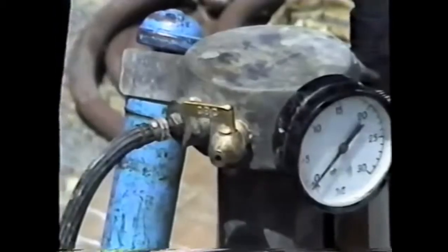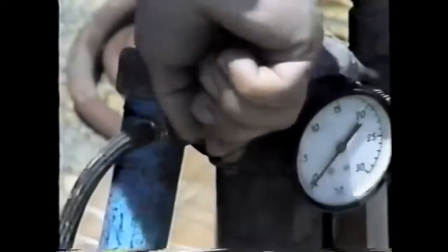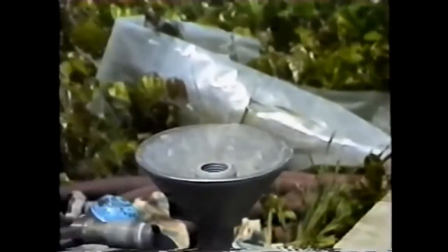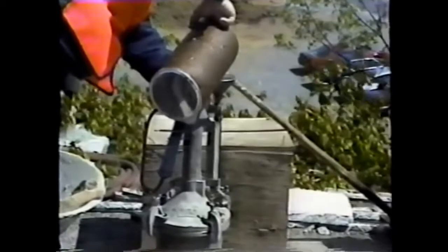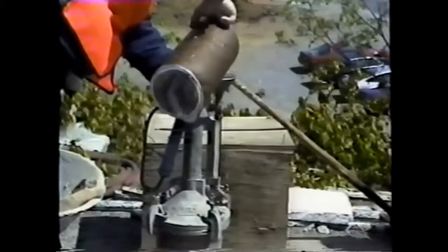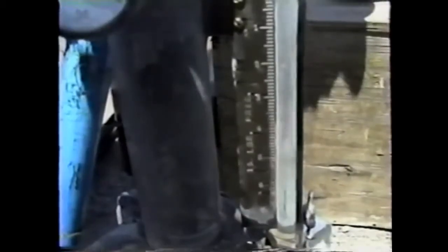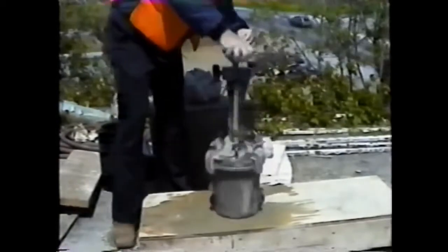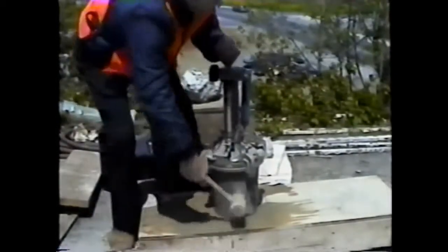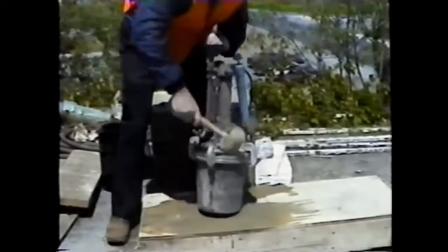The lower petcock is closed. The upper petcock and funnel valve are opened. And water is added until it rises to about the halfway mark in the standpipe. The meter should be gently rotated and tapped with the mallet to remove any entrapped air that may remain.